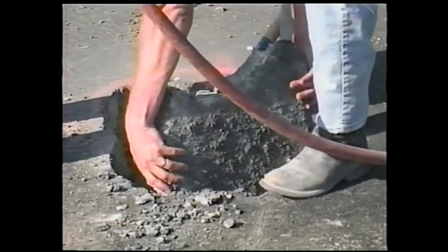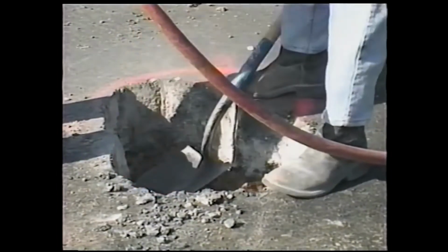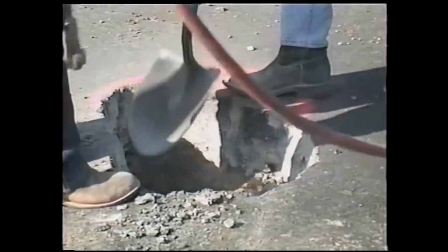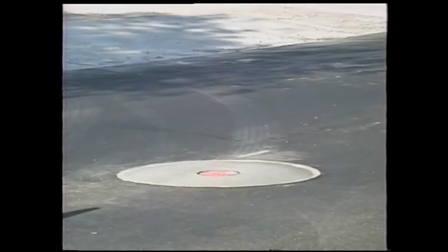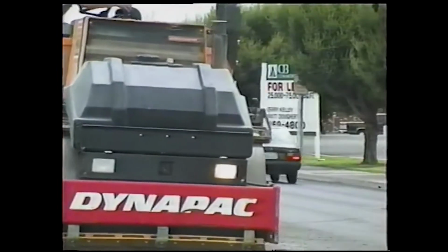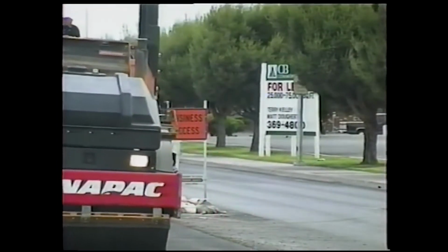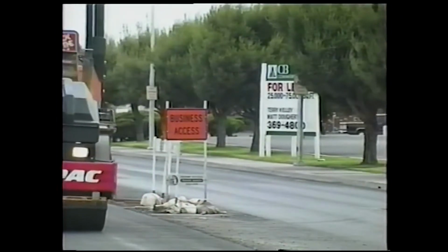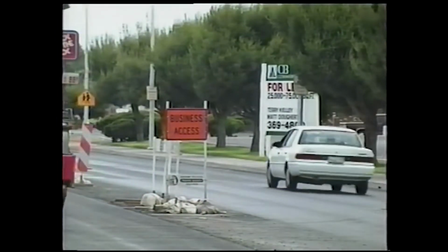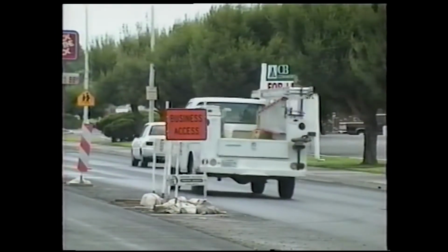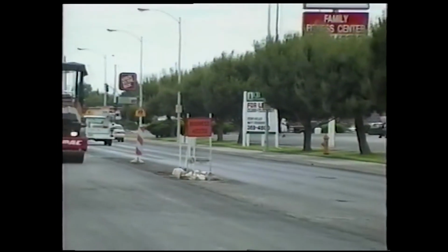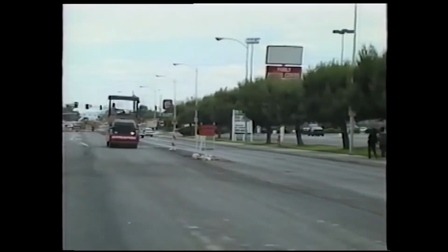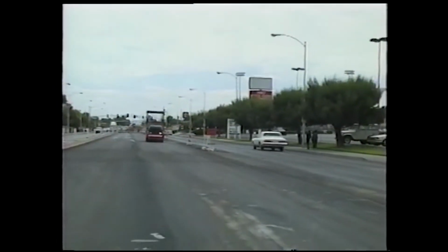Also, any planned crossroad utility cuts must of course be completed and patched before the new pavement is placed. Businesses should be contacted to arrange access times for employees if entrances and exits will be blocked by the paving operation. Private residents must be notified too. As the inspector, you should check out all such arrangements before paving begins.